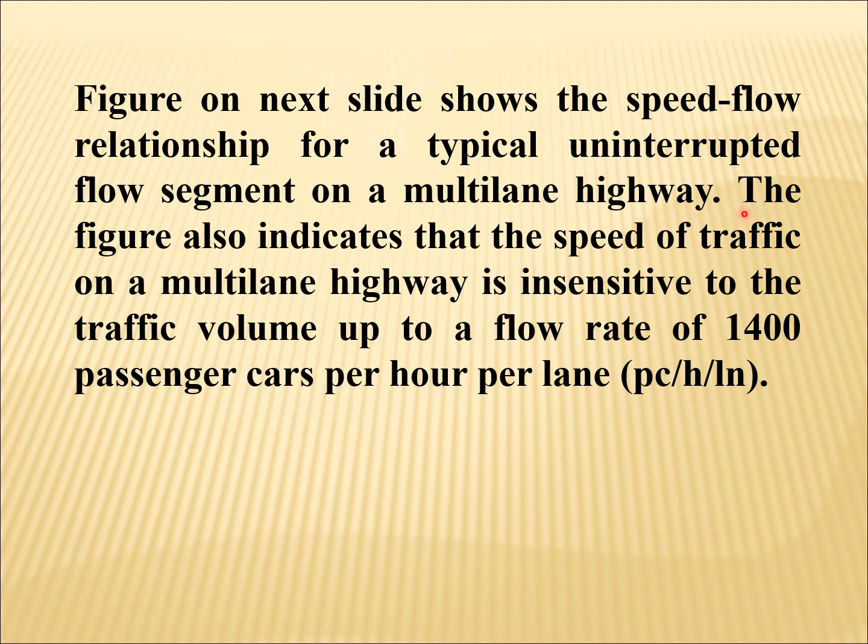I will repeat, the figure also indicates that the speed of traffic on a multi-lane highway is insensitive to the traffic volume up to a flow rate of about 1400 passenger cars per hour per lane.